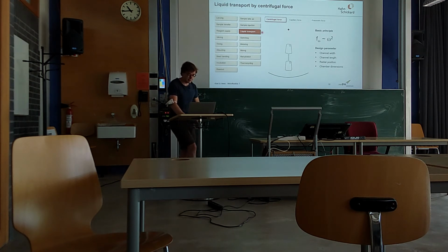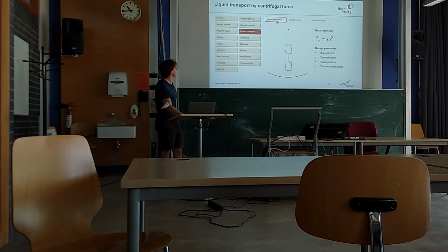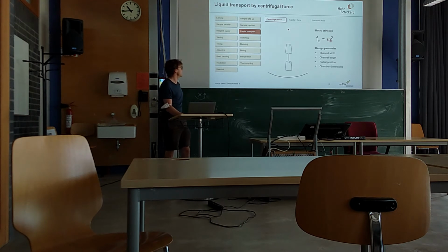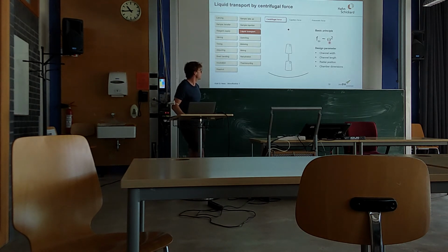Okay, then obviously liquid transport is also important here. And you can already see on the top that there are different ways of transporting liquid. The most important one is already a part of the name of this lecture, so the centrifugal force. Keep in mind, and that's really important, that it is proportional to the power of 2 of the rotational frequency. So at low frequencies, you probably don't have a relevant force, but if you go really high, it increases quickly, and the order of magnitude of the centrifugal force increases dramatically.